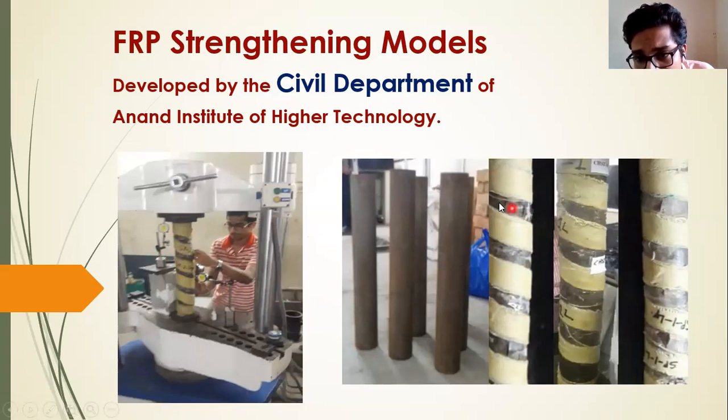That glass fiber surface mat has been used to avoid galvanic corrosion. In the case of aramid fiber, there may not be any chance of galvanic corrosion because aramid doesn't have any chemical, and it's very inert to the steel structure. So for safety purposes we have given it.